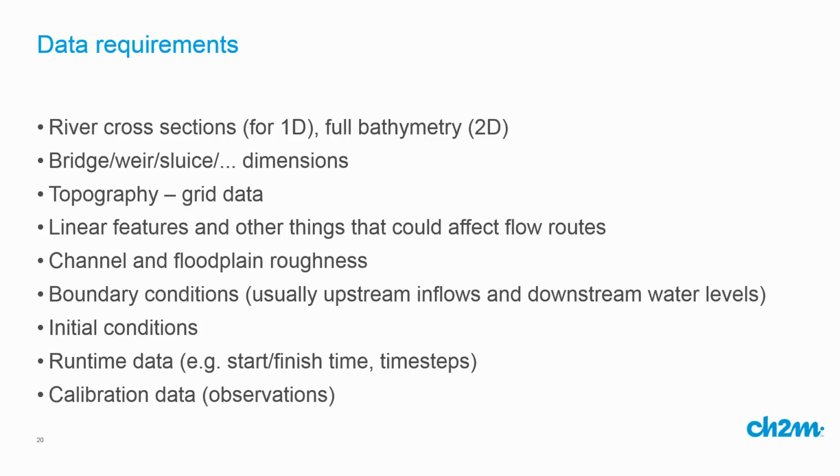We need to tell the system how much water to start with. Usually you have the floodplain as dry and you start with an initial condition, an initial water level in the channel that's consistent with the start of the boundary conditions, the start of the hydrograph that you're pushing through the model. Then there's some stuff to actually get the model running, so you tell it what solvers to use, the start and finish time, the time steps, and what types of results you want coming out, and that will enable us to do the run.